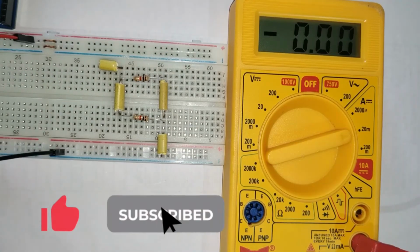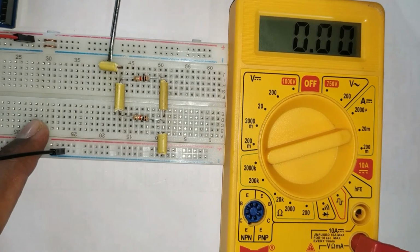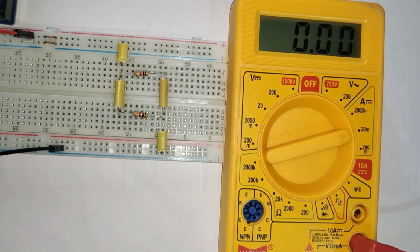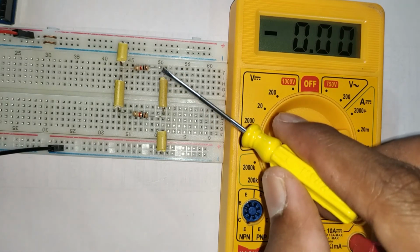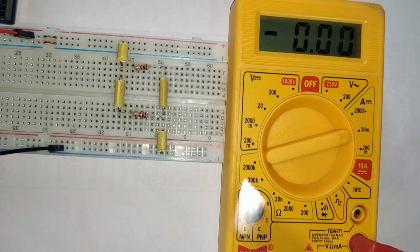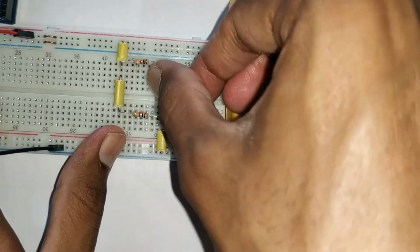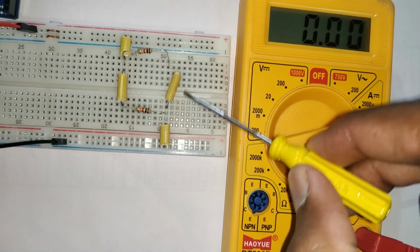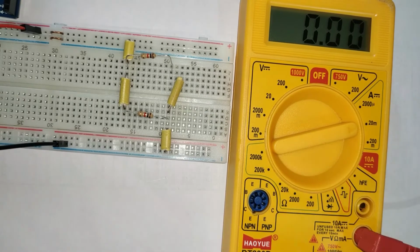Okay. Now we'll plug that back to the power supply and we'll see individual currents. Now our circuit becomes as it was previously. Now we have to measure the current across this resistor, this 1K. So what do we have to do? We have to put a multimeter in series with it. So we will remove this wire and put a multimeter here. I have put that wire two holes apart, so there will be no connection in the circuit now, because these two are not connected, so our circuit is broken now.